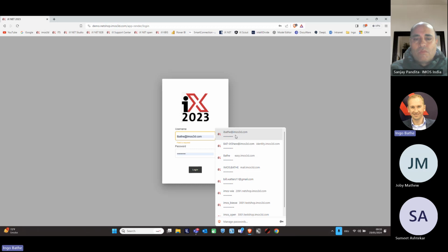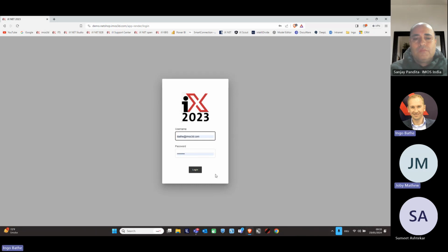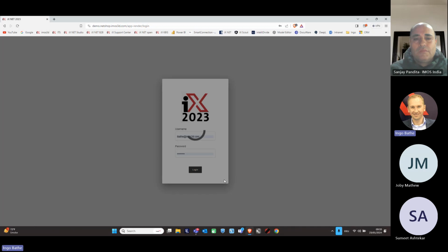What we have to do is we have to add to the library XML data, so the limitations. In your library, you have cabinets which you can stretch from 1 to 5,000 millimeter. For the sales, we have to give them a frame of options. So let's say minimum is 300, maximum is 900 in width, and so on. So this kind of limitation is important, so that the sales cannot sell something which you cannot produce. Sure, understood. But the library in general, yes, that is the foundation of everything.